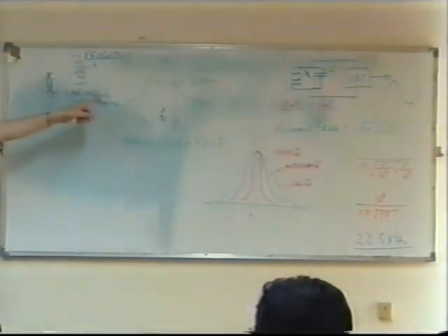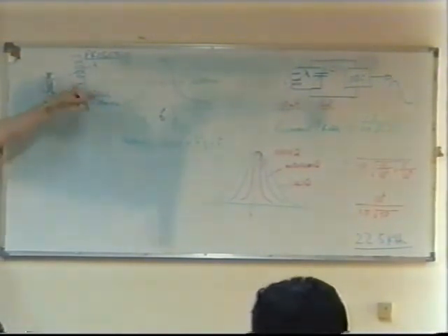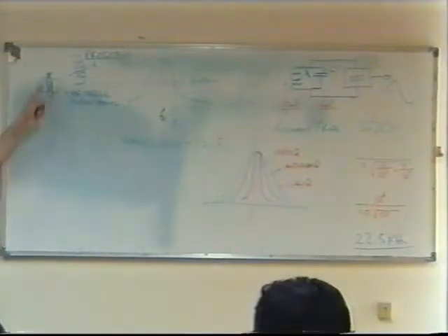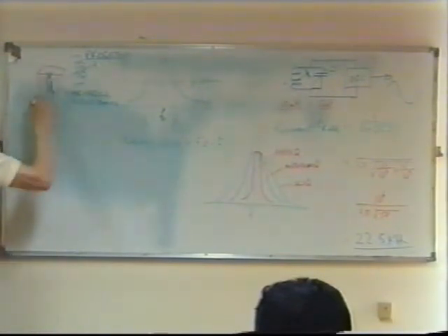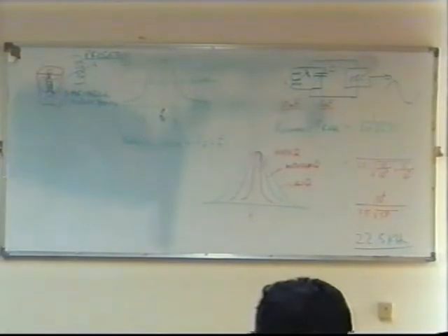That can produce a lot of problems. Secondly, it loses energy. If it loses energy, it's like increasing the resistance of the circuit. What does that do to the Q factor? Q factor goes down, doesn't it, if you increase resistance? So what they do is, they usually place this in a metal can with a hole at the top.